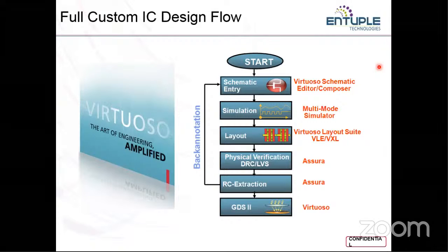So this gives rise to a parasitic capacitance, and its values are dependent on the dimensions of the layers, spacing between the layers, etc. This is how parasitic devices are formed, and to check the values of those parasitics and where all they are getting formed, that is what we do with parasitic extraction.